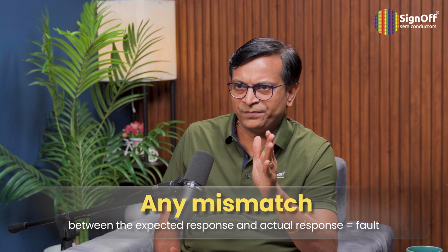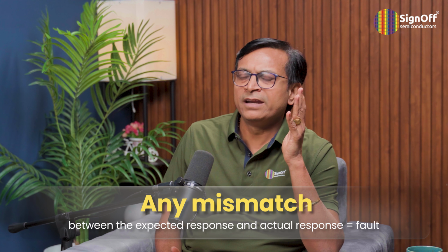And all these patterns are generated by using the ATPG tools. So if there is any miscompare, let's say you applied the stimulus, and when you are comparing the response from the design, you saw some flops are not matching. You were expecting one value and the flop is giving another value. At that time you can say that this particular flop is not behaving, or the logic before that flop is not behaving as expected, which is what the physical failure or the defect can be. And this is how the defects can be flagged using these ATPG patterns on silicon.